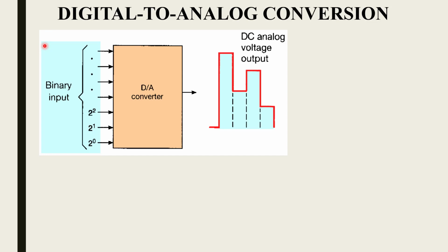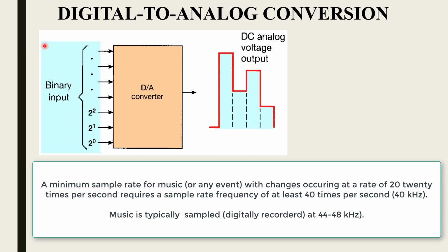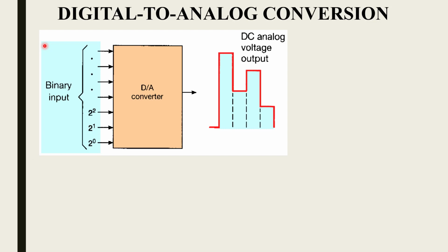But you know what? That's not even right, because things are happening so quickly that if we sample at 20,000, we're going to miss things. We're going to miss things that we'll be able to hear. This is called ghosting or aliasing, and it happens with video, it happens with audio, it can happen with any real analog occurrence that we're observing in an event, and we convert it to digital and then spit it back out later as analog. If we didn't sample fast enough, we're going to experience things that didn't really happen.